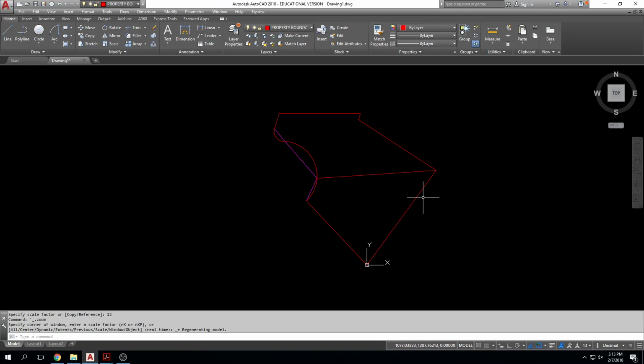Again, I like to draw a little line usually. Biggest mistake: students forget to scale it up, so it's not the right size. Second mistake: students scale it up more than one time. You look at it and think, oh dang, walk away, get a drink, come back, and wonder, did I scale it up by 12? I can't remember. How do you tell? The way you can tell is you can measure it.